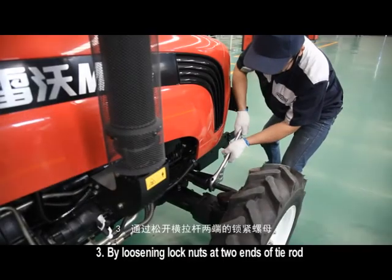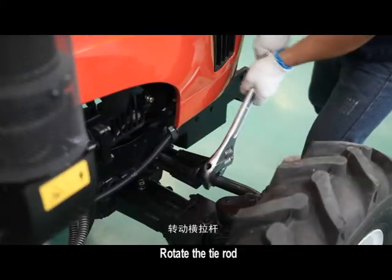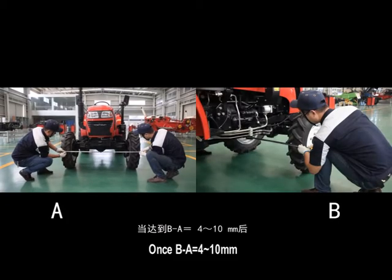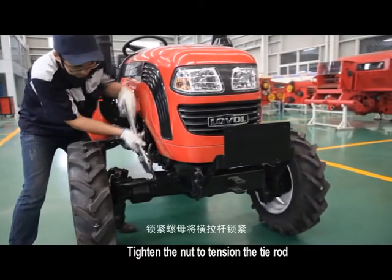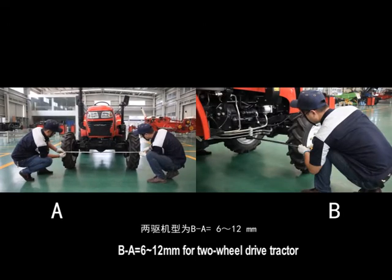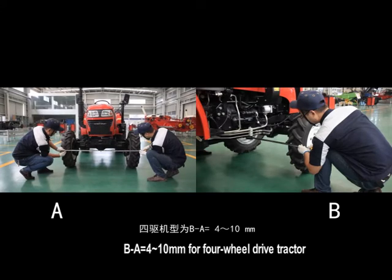By loosening lock nuts at 2 ends of tie rod, rotate the tie rod to extend or shorten the rod. Once B minus A equals 4 to 10 millimeters, tighten the nut to tension the tie rod. B minus A is 6 to 12 mm for 2-wheel-drive tractor. B minus A is 4 to 10 mm for 4-wheel-drive tractor.